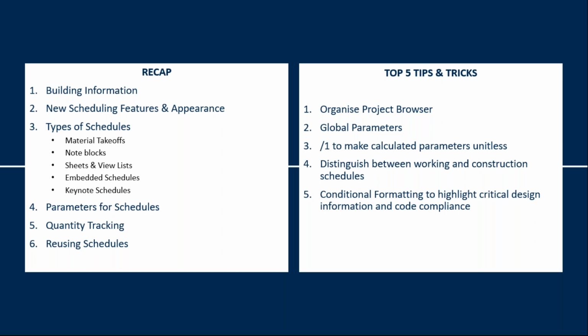And then we looked at how to create a global parameter for information that will be applicable for all your projects, relating to densities and cost in particular. And then we also looked at how you can reuse the schedules. You can have them saved in your templates, or you can simply use the insert files tool to copy schedules from one project to another.